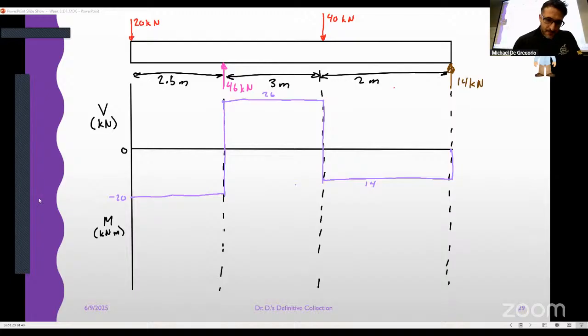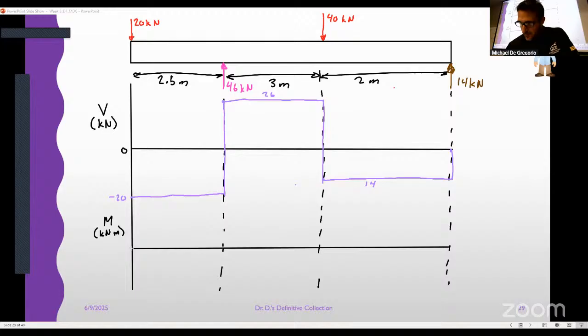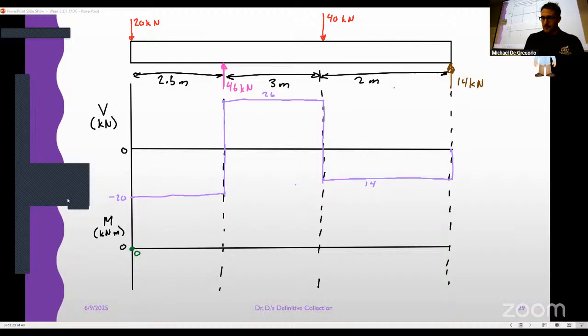Kilonewton meters. We'll put our 0 line in. Right below it, we're going to do the same thing. All right, what was our shear at point 1? 0. I'll make sure I put 0 here as well. Okay, what about at cut 2? Negative 50. We'll say that that's here. Negative 50. Okay, what about the next one?